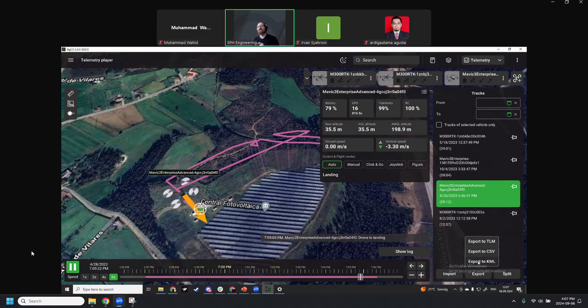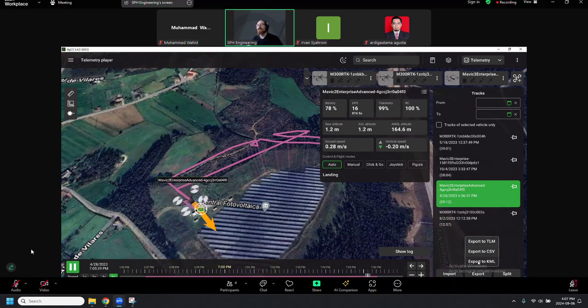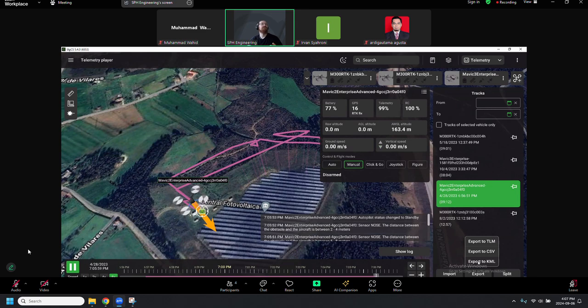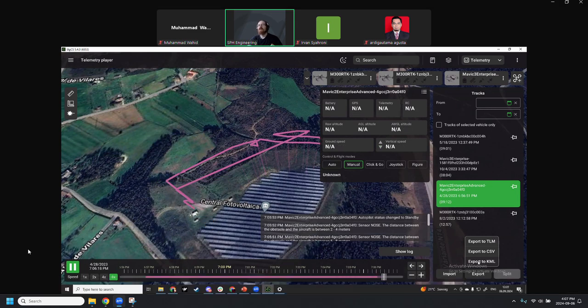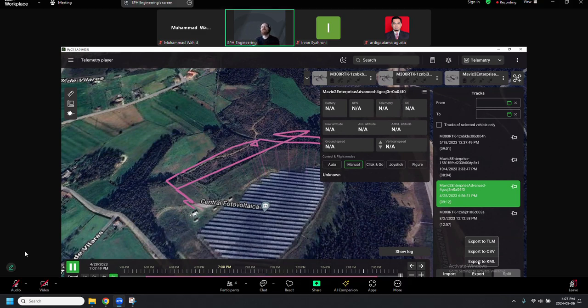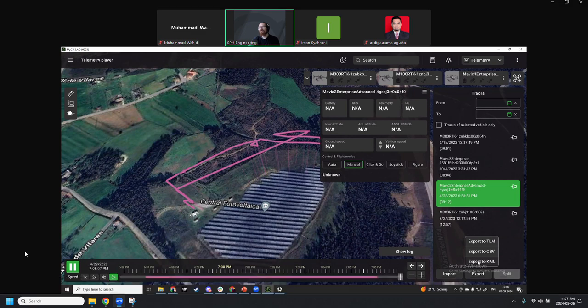AirLink, and some others. And for example, for some very specific flights, you might want to fly your route manually, record the telemetry. So you connect your drone to UGCS, it records your telemetry. You have a nice view of the surroundings. You take the telemetry, export it as a KML file, and then import the KML file back into UGCS so you can reproduce your manual flight, but automatically.